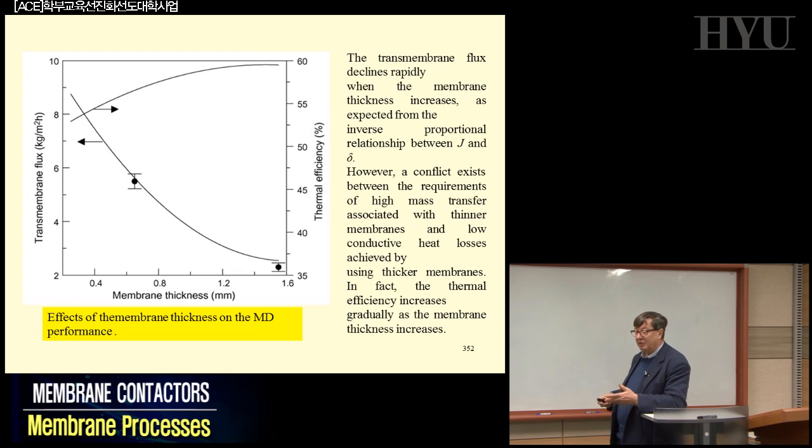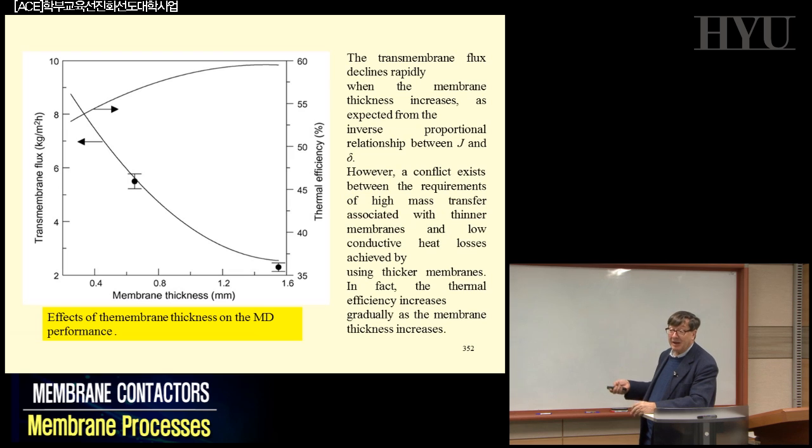So you have to optimize in terms of thickness or in terms of thermal efficiency that is going up. Your colleagues, students, are working just to try to optimize thermal efficiency in terms of flux. Both of them are important for the final cost, but they have totally different behavior. One of the reasons for which the existing commercial membranes, produced for microfiltration, are not appropriate for membrane distillation is that for membrane distillation, you can increase the thickness and not decrease it.